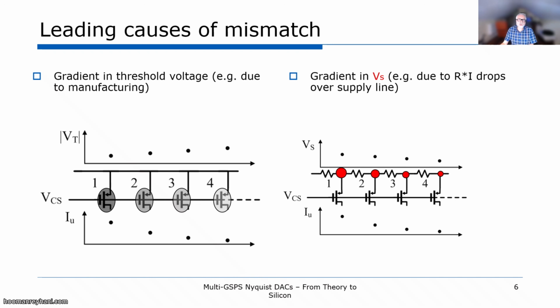The topic of non-idealities is one of the most important ones. Very small imperfections can have visible impact on the DAC spectral performance. Understanding the source of non-idealities is the first step toward their compensation. For instance, any array of transistors will be subject to manufacturing gradients or to power line IR voltage drops. This, in turn, will lead to corresponding parametric shifts. If we design our DAC so that the input code control for these devices leads to gradients building up errors on the output, then strong harmonic distortion will develop.